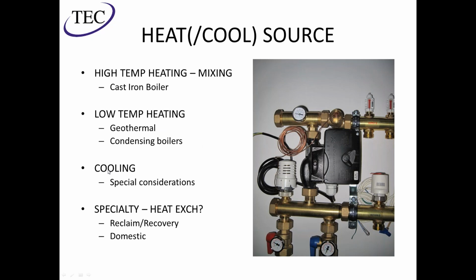With cooling, I mentioned briefly, the installation and estimating are all the same. The special considerations that you'll need to take are more on the control side, making sure you're not exceeding the dew point and whatnot. But they will, in general, have larger diameter tubing and closer spacing.